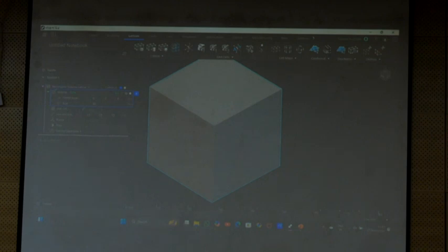So here I will show you the strut based lattices. As I told you, with the first method, double press on it and you will see the available options. I will take this first one, graph unit cell. It is asking for the unit cell, again empty. There is a ribbon button; press the ribbon so that you will see the available unit cells here. These are all graph unit cells, meaning line diagrams. With line diagrams we can generate.